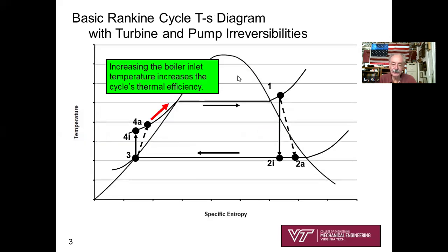And so what are we trying to do here? Well, we're trying to improve the thermal efficiency of the plant. And I guess we could say, yeah, we're going to improve the thermal efficiency of the plant because we're going to take the feed water that's up to boiler pressure and we're going to recover waste heat from the exhaust stream and we're going to add it. And so we're going to increase the temperature, therefore the enthalpy, of the compressed liquid going into the boiler. So I think we could argue that we are improving thermal efficiency of the cycle, the more I think about it.